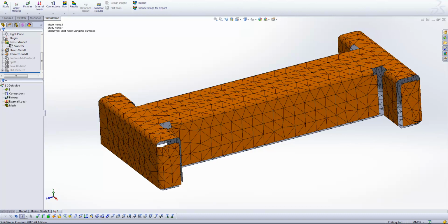So it's going to tell us based on the thickness of that material, which SolidWorks has picked out automatically for us, it's going to work out the stress values on the top and bottom surfaces with respect to the geometry that we've got on the screen now, and it's going to extrapolate out to the extreme top and bottom surfaces of our original model. And that's absolutely fine. That's something that we may want to use straight away. Obviously I'd refine this mesh a bit further, but for now that's absolutely fine. So let's have a look at another strategy.